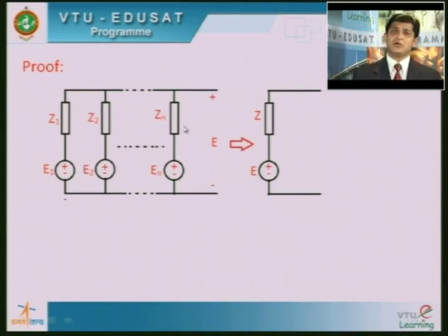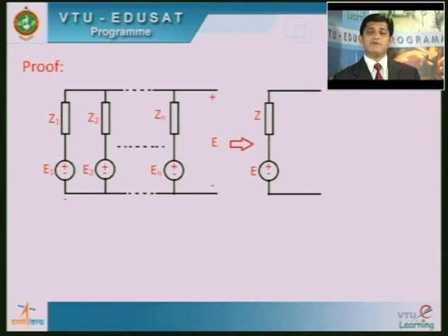Another thing that node analysis deals with is, after we mark the node voltages, we need to look at the currents. Let there be any number of branches, we need to have the currents in those branches. And after that, there would be some currents entering the node and some currents leaving the node. What does KCL tell you? KCL tells that the sum of the currents entering should be equal to the sum of the currents leaving.